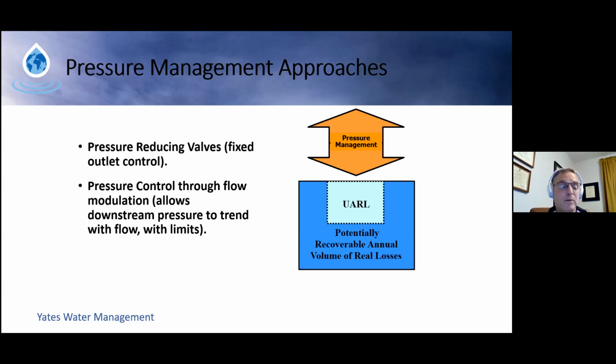For those of you who operate firefighting systems, you know you can't let your pressure drop too low because during a fire, you could produce negative pressure in your distribution main, which will cause you a whole lot of hurt if you do that. You will have one mess on your hands. You'll be breaking mains all over the place. So here again, we show this lovely graph to get the point across that pressure can work in your favor, or it can also increase your leakage if you don't manage it.